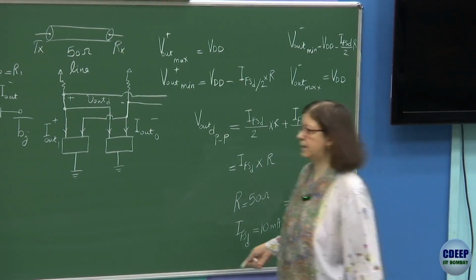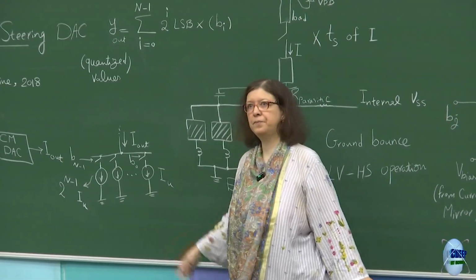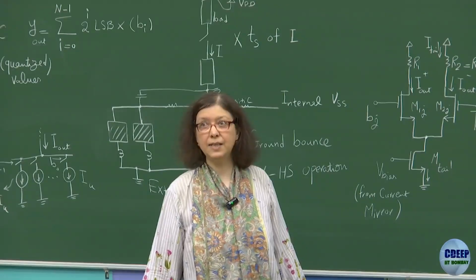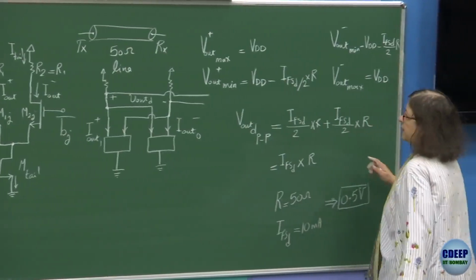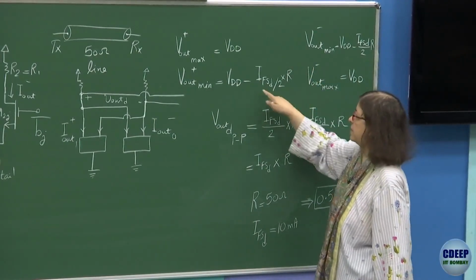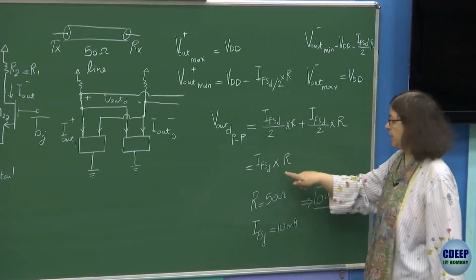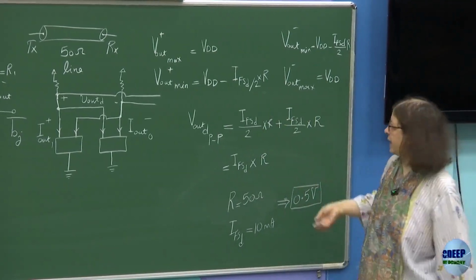Full scale single-ended is the binary weighted sum of all these currents, single-ended. The sum of all those currents single-ended is the full scale. Because you see that if I look at the V full scale, I have this value as the swing. If I look at the differential, I will have double of that. That's why I define this as V full scale.